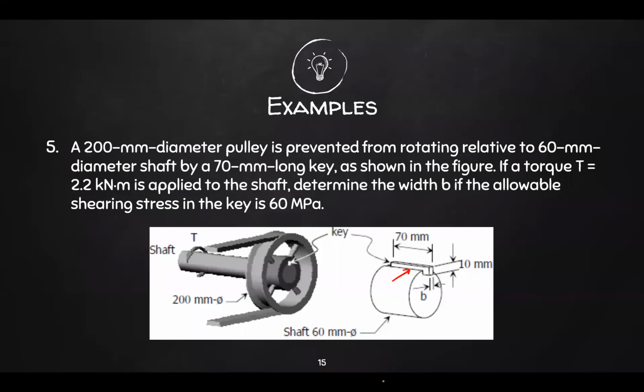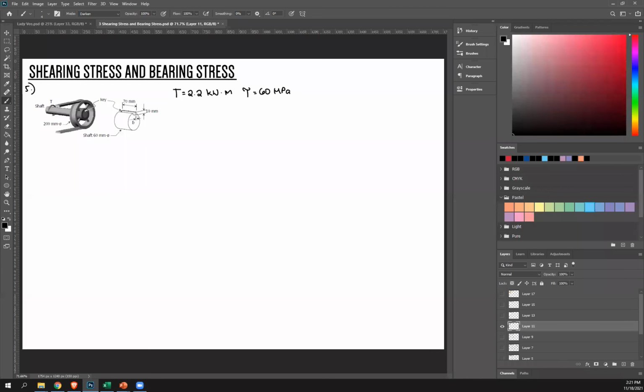And then the parallel area to that force would be the portion here. And this force is due to the torque of your shaft. And remember, torque has the equation RF, and so F is what we're gonna get. So once again, that shear force is due to the rotation of this shaft, and it's gonna be applied over this area.